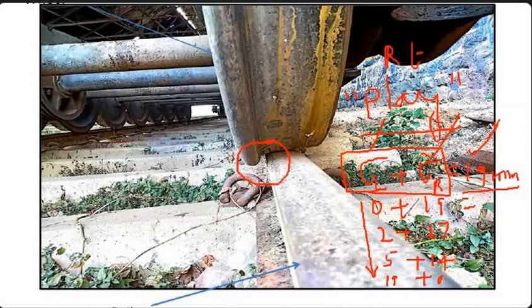So we have one video. That video I will play for you, so you can understand how the play is changing. Whenever our wheel set is moving over the rail table, this play will keep changing from 0 to 19 mm. Say first time, say here we have 7 mm. The left side also, 19 minus 7, 12 mm will be there. So that means total play is always fixed. 19 mm is fixed.